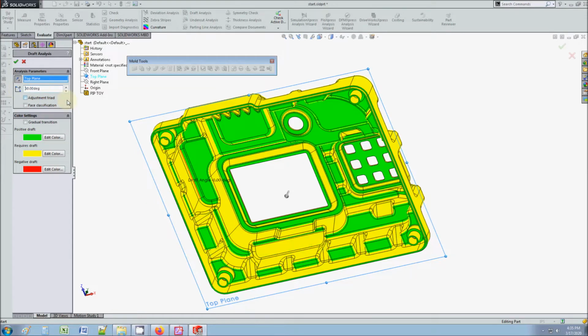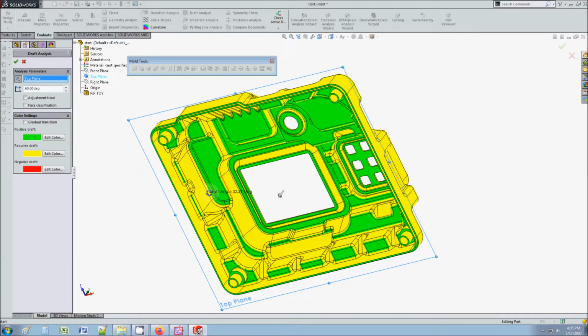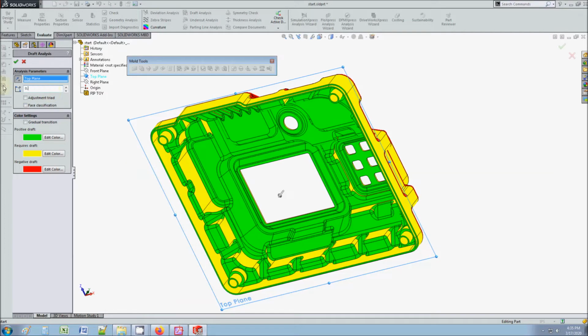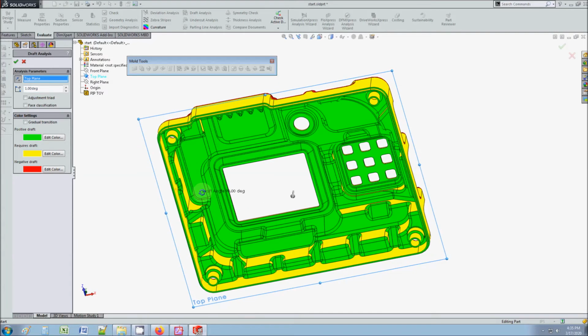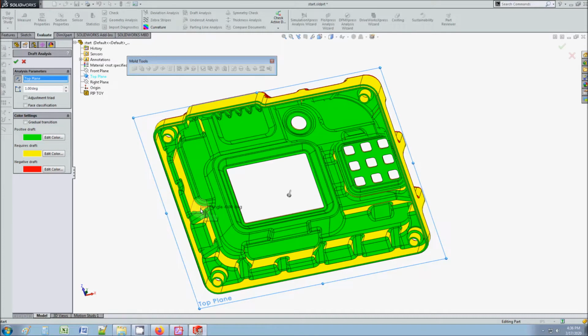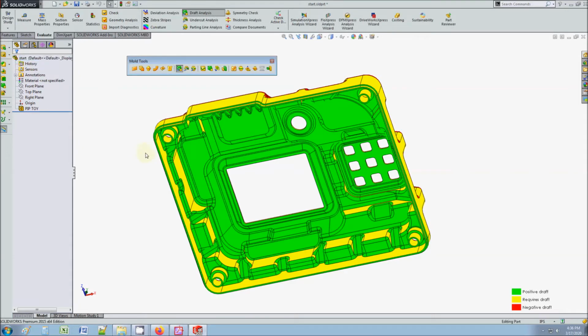So it really depends on the tolerance that you set. And ideally, you don't want to have an orthogonal 90-degree surface. That's not good. Maybe a degree or 0.5 of draft could be okay, but try not to keep it orthogonal if you don't have to, just so it makes it easier. We're going to stick with this, but ideally you'd optimize this. You'd add a little bit more draft here and there to make it really smooth when it ejects. Okay, so we're just going to click OK.